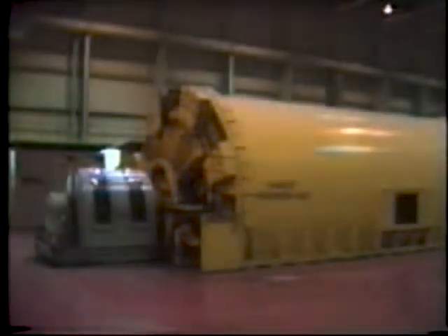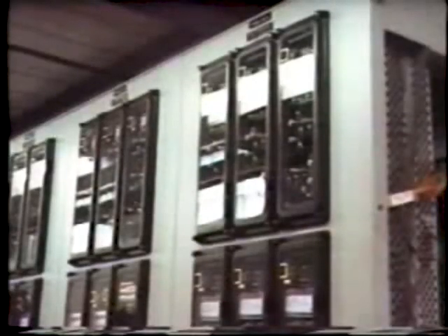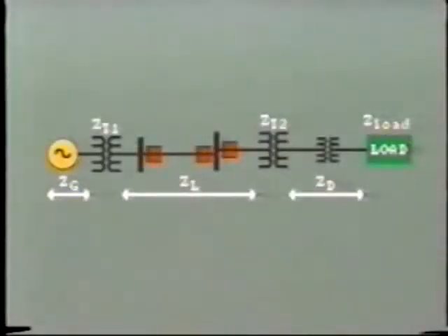In practice, it is probable that the generator automatic controls may attempt to increase generator internal voltage in order to compensate for some of the voltage drop downstream. However, this would take some seconds and therefore should not interfere with the operation of protection relays, nor with our studies of fault characteristics. Let's take our study a step further now and consider the magnitude and phase angle of the various impedances. Here is another single line diagram, but this time of a more complicated system.